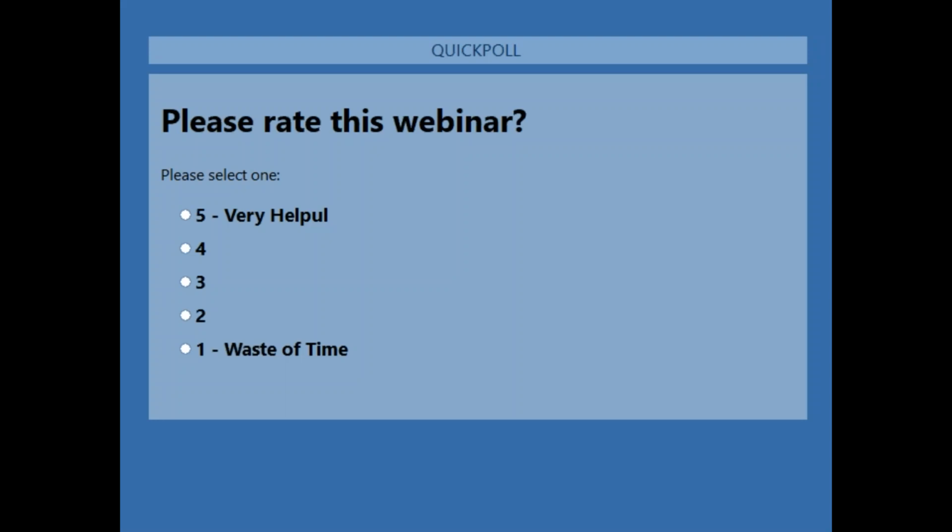You'd be really pushing your luck to say I want to get an 8-inch inlet on my VAV box. Not that it would be impossible, but you'd have to talk to your VAV manufacturer and specifically size it for that, and then also deal with the cross flow and its ability to measure pressures at that range. And the VAV box controller, you'd have to get something special to measure that pressure. It's not going to normally be set up to measure 8 inches of static either.